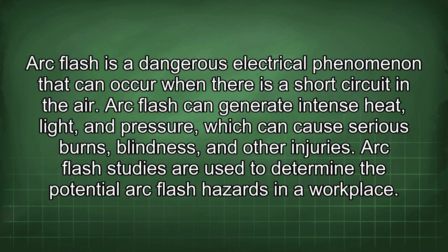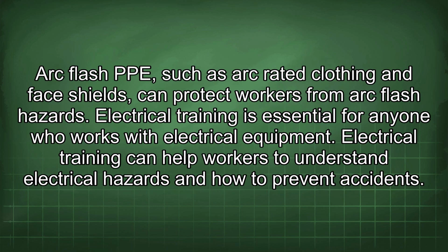Arc flash is a dangerous electrical phenomenon that can occur when there is a short circuit in the air. Arc flash can generate intense heat, light, and pressure, which can cause serious burns, blindness, and other injuries. Arc flash studies are used to determine the potential arc flash hazards in a workplace. Arc flash PPE, such as arc-rated clothing and face shields, can protect workers from arc flash hazards.